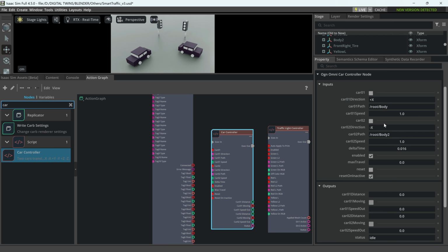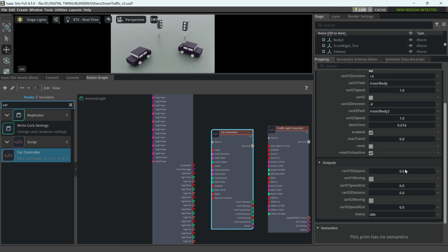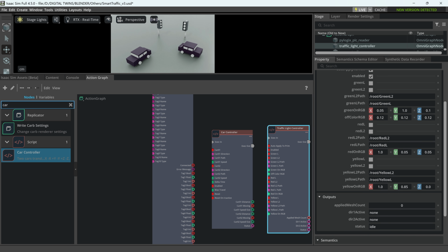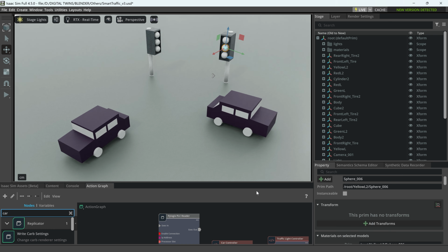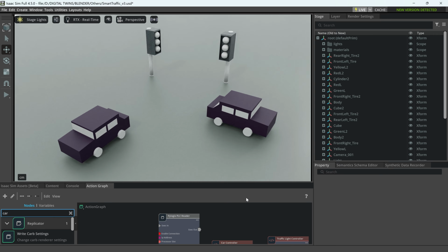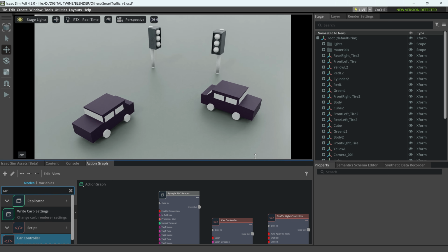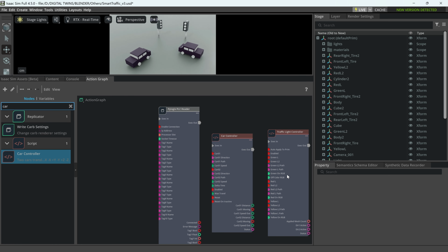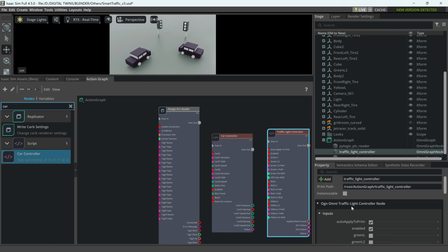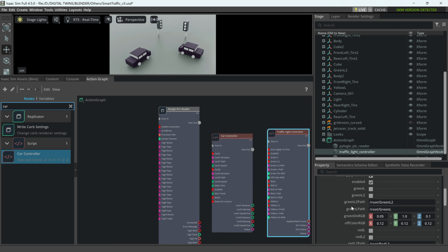One important consideration is synchronization. Isaac Sim and the PLC execute independently, so communication must be fast enough to keep both systems synchronized. The PLC always remains the deterministic controller, while Isaac Sim only visualizes the process.